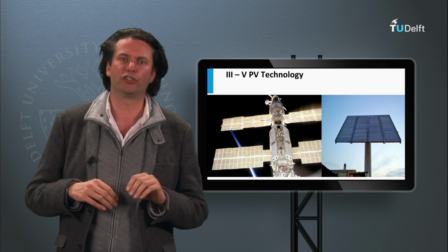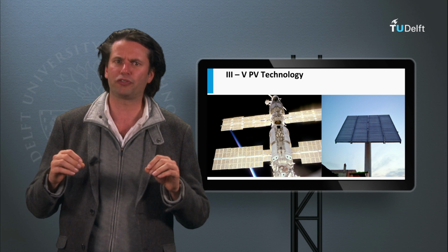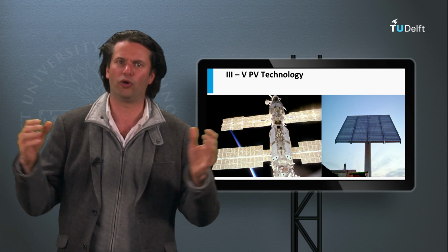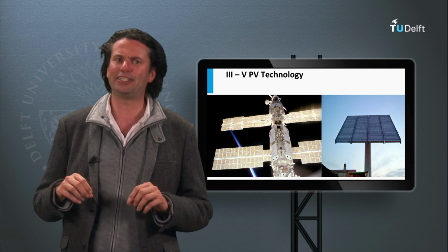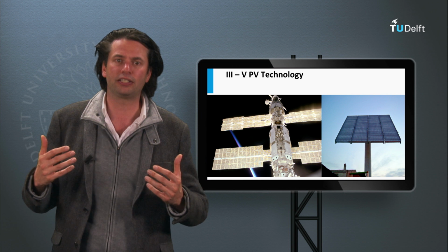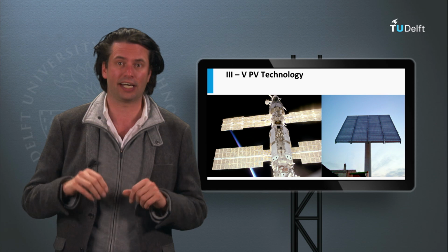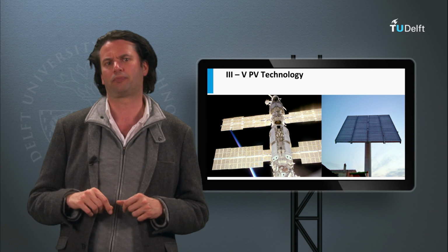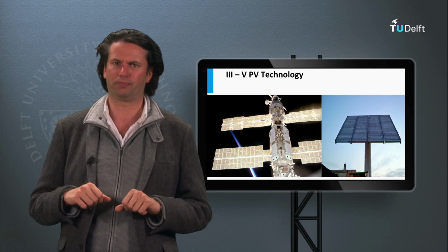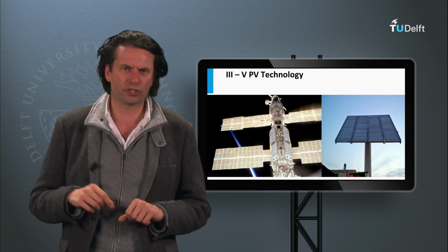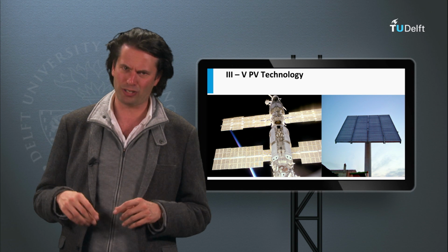The dollar per watt peak of a small expensive III-V multi-junction device can be improved by concentrating the irradiance of a large area on the small solar cell device. An advantage of concentrating sunlight is that the open circuit voltage is increased with irradiance as well, as long as Auger recombination of light-excited charge carriers does not become dominant. Important is that the small solar cell devices have to be actively cooled. As will be discussed in weeks 7 and 8, the performance of PV devices goes down when they heat up.